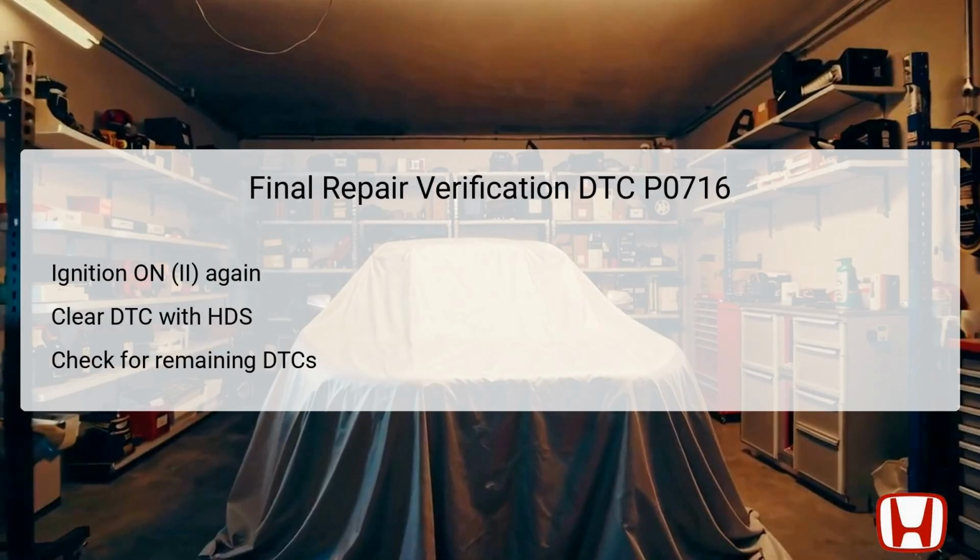The final repair verification process requires turning the ignition switch to the on position. This action not only powers up the electrical systems again, but it also prepares the unit for another round of diagnostic checks. Clear the DTC by using the HDS once again. This is crucial for verifying that the previously diagnosed issue has been successfully rectified.